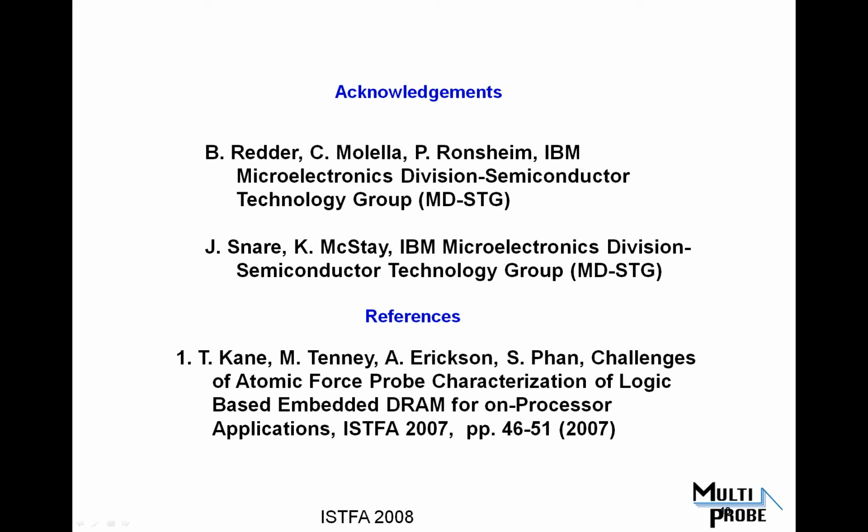So you're going to place a probe on a source and a probe on a gate and measure the capacitance directly between those 2, or a probe on a bulk on a P-well or something relative to a gate. So that's the way that you'll carry out those measurements. Does that answer the question?